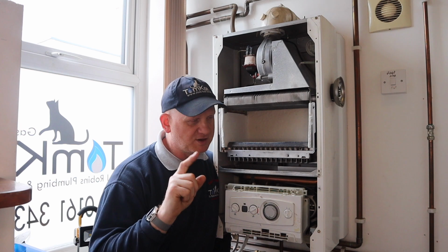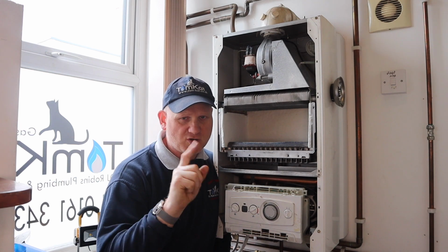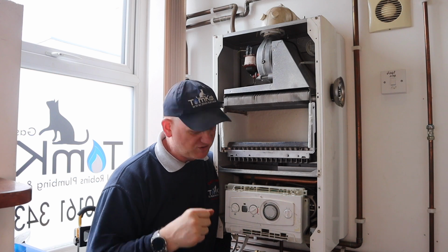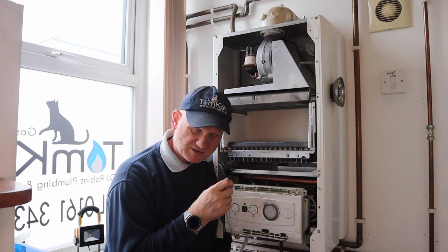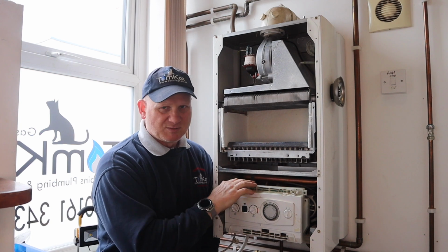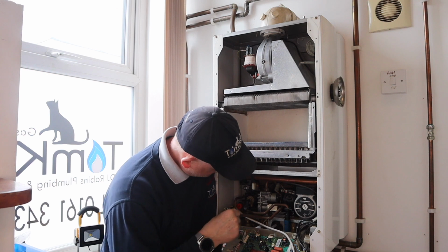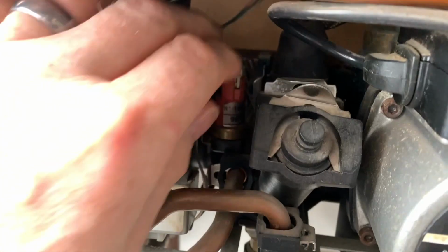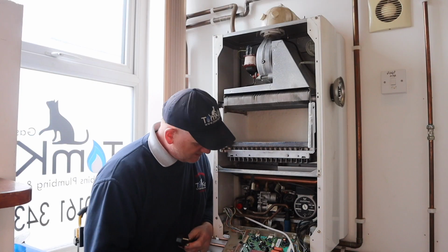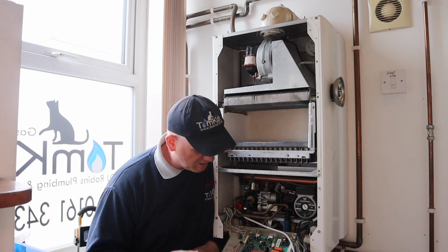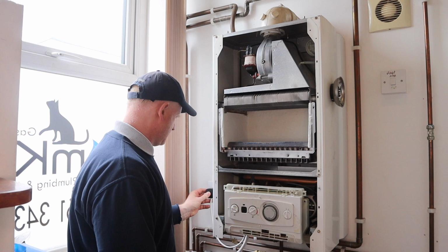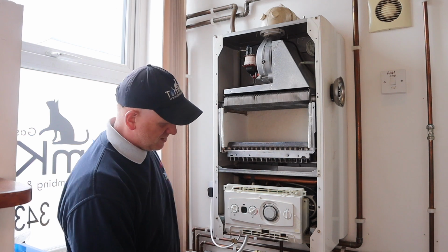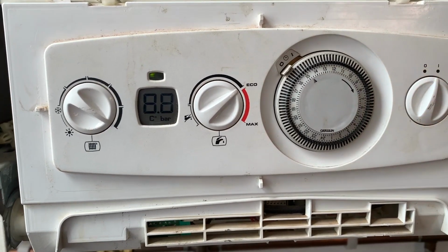Now the next fault I'm going to do is I'm going to disconnect the pump proving switch, or the low water pressure switch, or the thing that puts the actual dial on. And again, I've got this unplugged because this is still uncovered. So literally I'm just going to unplug this low water pressure switch, close it back up, plug it back in, turn it back on. So again, should go through the proving.